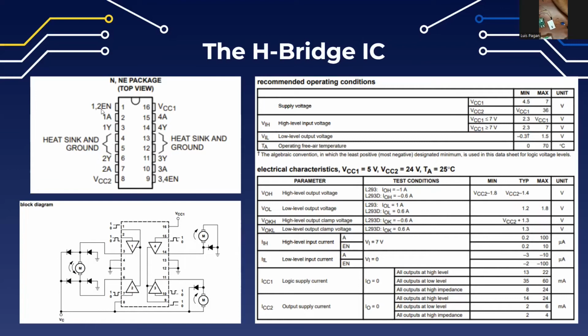What you can also do with this enable is control the speed of the motors, because whatever range of voltage you give to the enable pin will be reflected in the output. Let's say you give this 2.2 volts, the output is also going to match that. So this is good. You're going to plug in the PWM pin here when you're setting the speed of the motors.